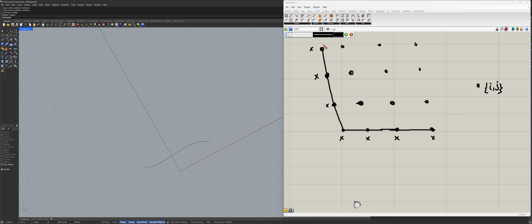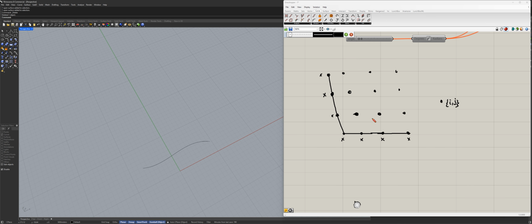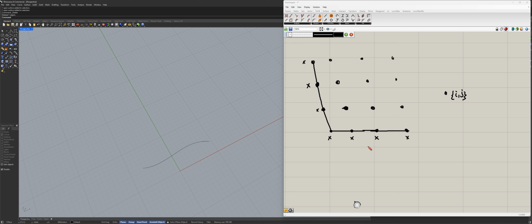The process of creating basis functions and actually constructing a surface is called tensor product calculation, or tensor surface product, or some people call it tensor product surface. It's not important. So basically, the system will construct another matrix using the cross product as well, but this time it takes all the possible combinations of the basis functions. What does it mean? It multiplies one basis function by another, these by these, these by these, and so on and so forth.